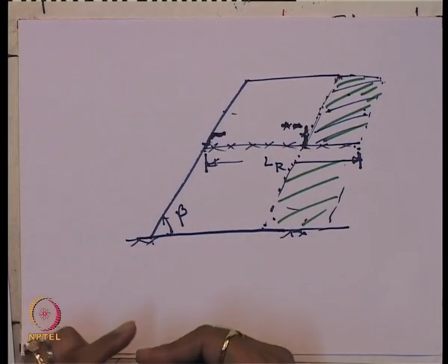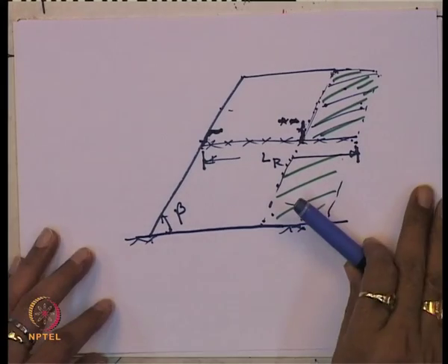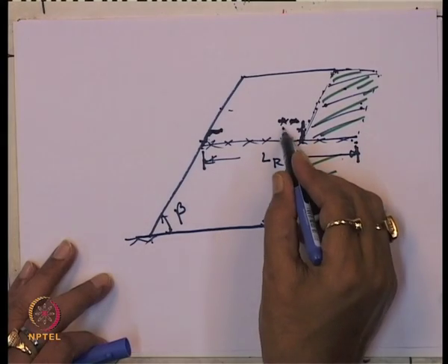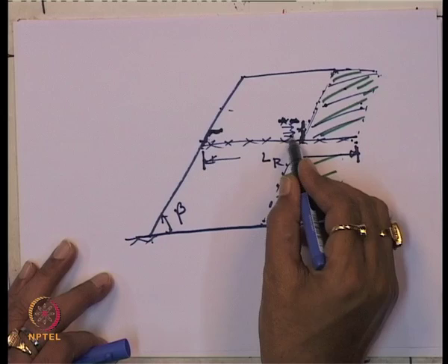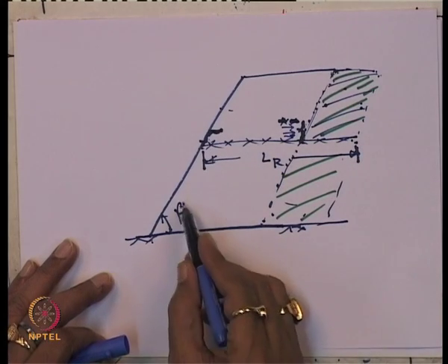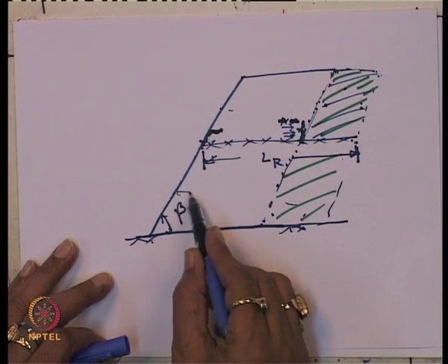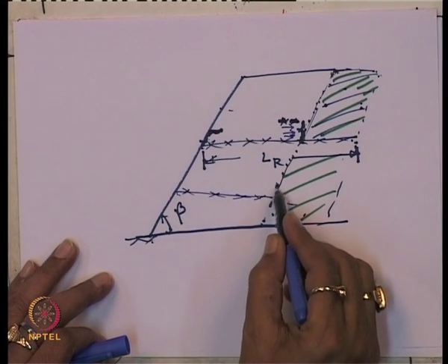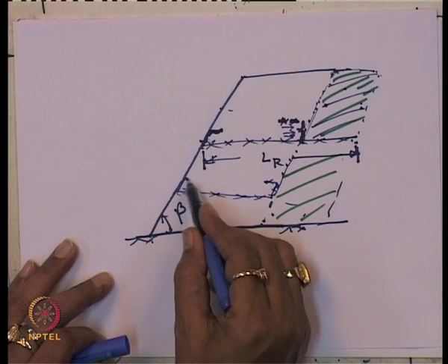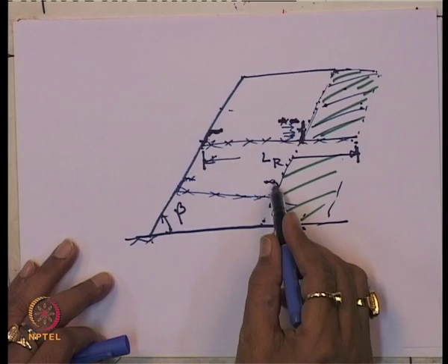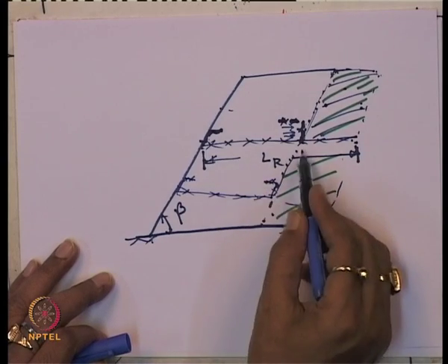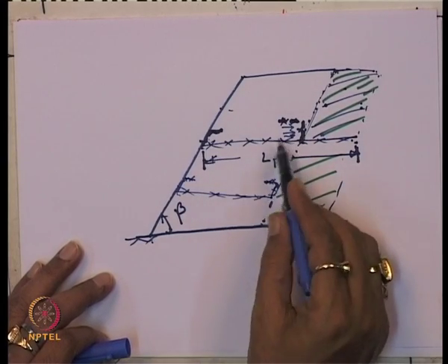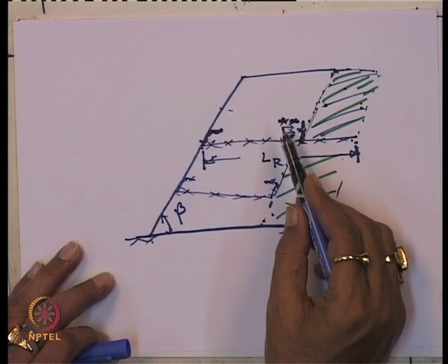So, there will be a development of the passive resistance here. Like this, you can place another geogrid material like this. You are giving the back wrapping technique. So, this is what we call the back wrap technique for reinforced soil slope.